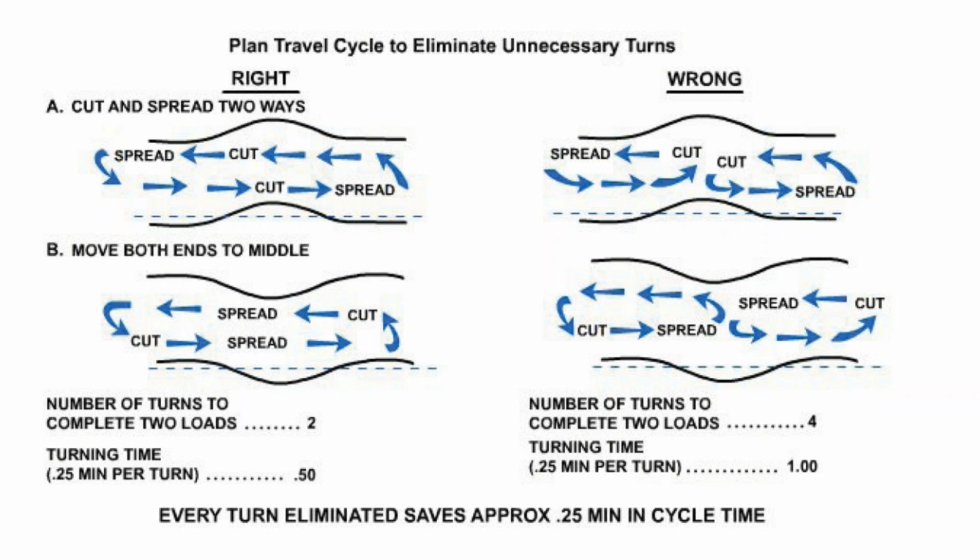It's a lot of expense. The reason that we use them is that very frequently in road building and in site leveling, it's very efficient to use our scrapers in combination. So they're picking up, they're traveling 2,000 feet, and they're dumping it. We could try that with a dozer, but 2,000 feet will kill us.